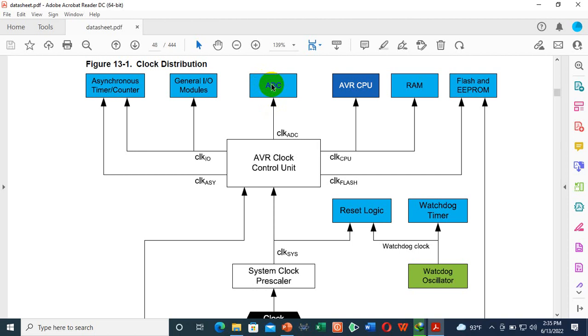Are sampling and conversion two different things? No, this is simple. By sampling, you get the data. Let's say in the 0 to 5 volt range, you get samples of every value, let's say 0.1, 0.2, 0.4, 3, 5. Every value gets converted to a digital value between 0 and 1023.